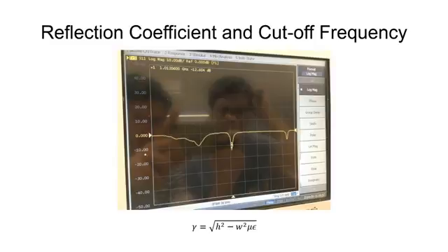And there are other points I want to talk about in here, like the frequencies below cutoff. There is also a drop in those frequencies. The reason for this is again the gamma value. In that range, the gamma value is real, and since it is real, there is attenuation, and because of the attenuation, there is this drop.